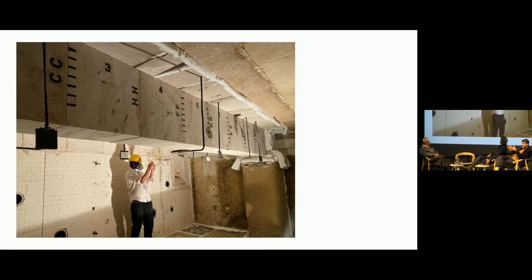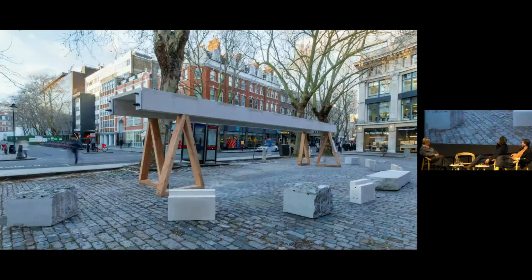With concrete, because the water sits inside it, when you burn concrete the water turns to steam and blows the face off the concrete. So you get explosive spalling, it exposes the rebar, the rebar melts, and the beam falls down. For some reason, limestone doesn't have those trapped vents. The steam freely vents. We didn't get any explosive spalling. Because it's a post-tension beam, the reinforcement is a lot further inside than it would normally be, so it's not as exposed to the fire. So we got 3-hour fire resistance from this beam, very encouraging for Amin's building, which we'd already built.